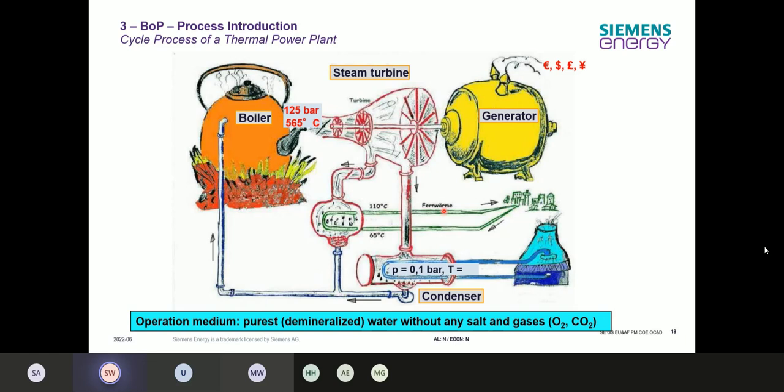This over here is, sadly in German, district heating. So you have a return line which comes back with a colder temperature, and you're sending it back over here with a hotter temperature. What we're doing is taking steam out of the turbine, increasing the water temperature of the district heating system, and sending it to industry and to households in the city.